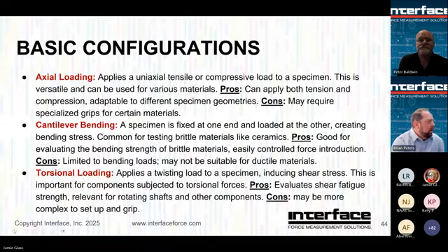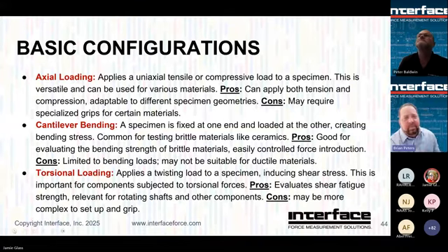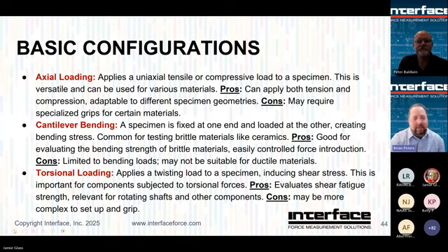All right, sir. All right, so testing configurations, data interpretation. So we'll go through this kind of quick, but when you're setting up a fatigue test, there's different ways that you can apply loads to a test article, right? Very simple, very easy axial, specifically vertical, right? That's the easiest and cleanest test setup. Cantilever bending, also very popular for fatigue testing. Say you're wanting to test something that's under a side load, you need to fixate that. The good news there is you're likely going to be using an axial force introduction, which is good.